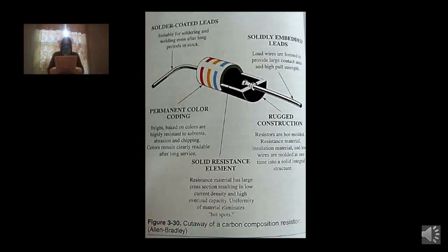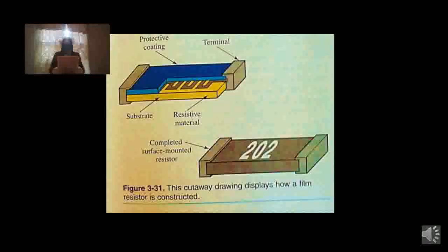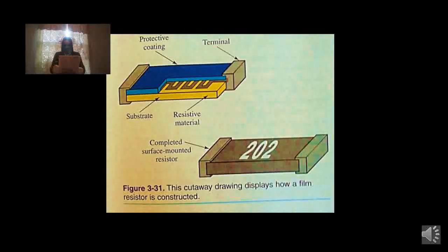The thin film resistor is similar to the molded composition resistor in appearance and function. However, the thin film resistor is made by depositing a resistance material on a glass or ceramic tube. A photographic process is used to deposit this thin film. Leads with caps are fitted over each end of the tube to make the body of the resistor. Thin film resistors are usually color-coded.